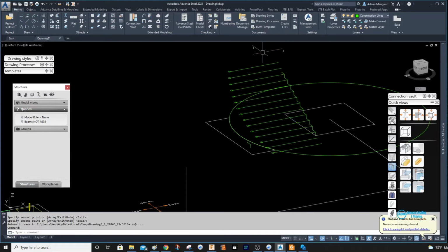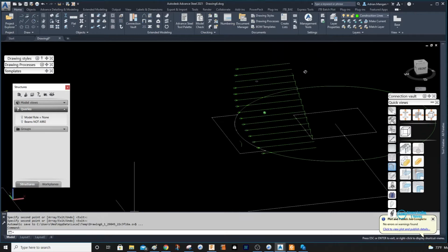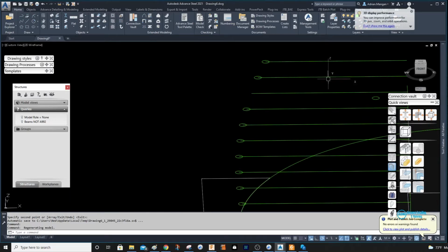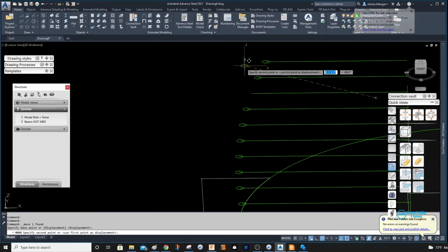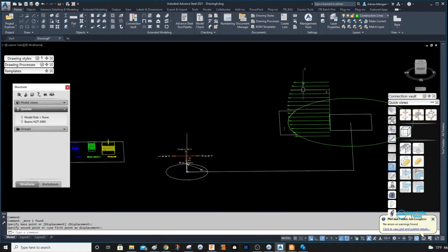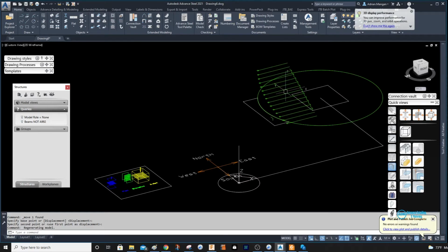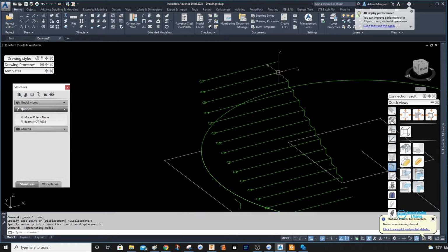I don't have to work off the threads, because you can't snap to the end of where I've cut the threads. I can only snap to the system lines. So obviously one of these got thrown off in the distance, which, as I mentioned, is an issue I have with 2021.